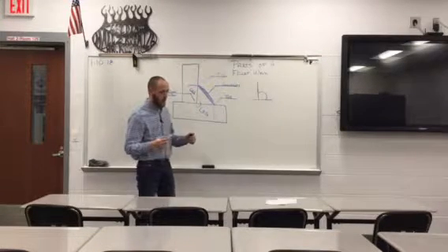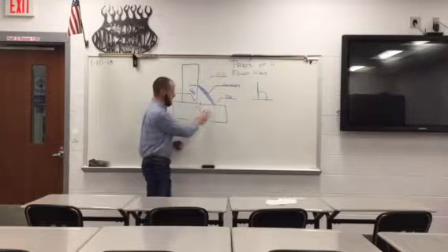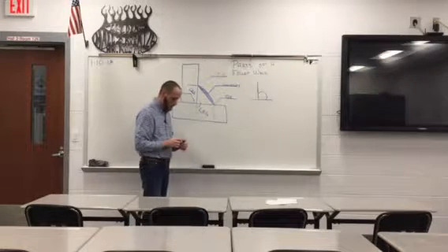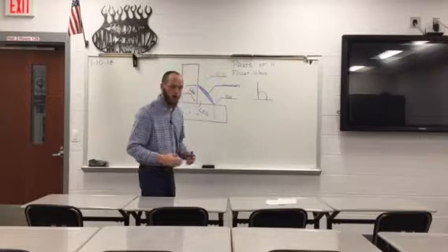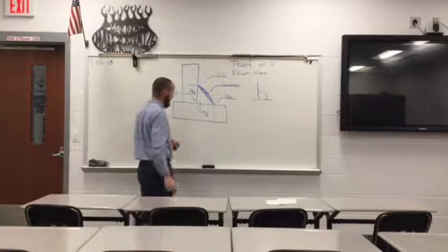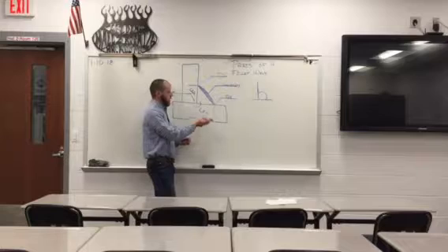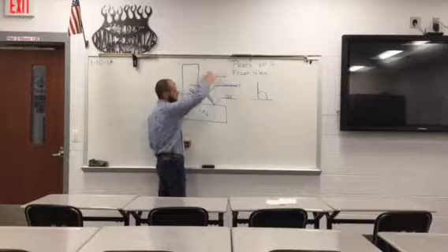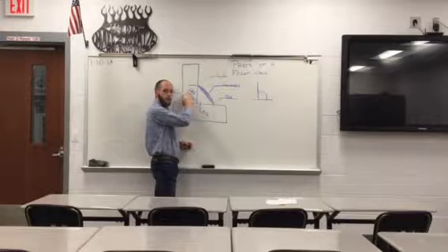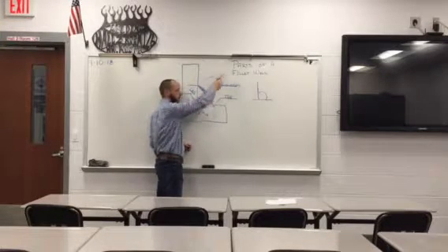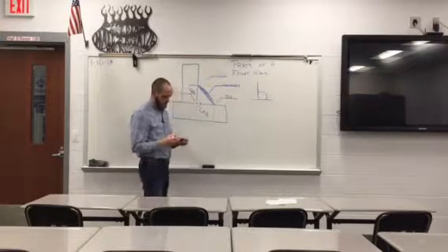Now, let's say we don't have equal legs. Let's say we have a 1/2 inch here and a 1/4 inch here. That's an unequal leg weld, or uneven leg, some people call it. Chances are your angles were too steep. You angled all your weld metal to the bottom plate and not both pieces. We want a nice 45-degree work angle coming out from the joint root.